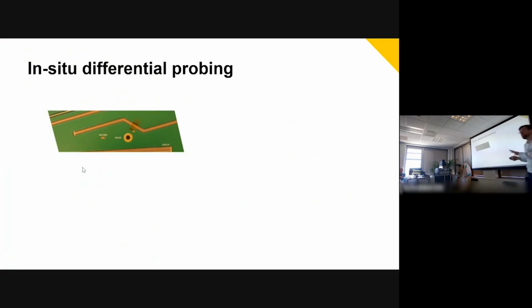Okay, but this was probing still with a dedicated probe landing pad. So it means you had to think about it beforehand. What if you have a bare board with a problem, with about 10 centimeters of trace, a bit of strip line, a differential via, trace, 2 45-degree bends at an outer layer, something like that. Can you probe and draw meaningful conclusions?